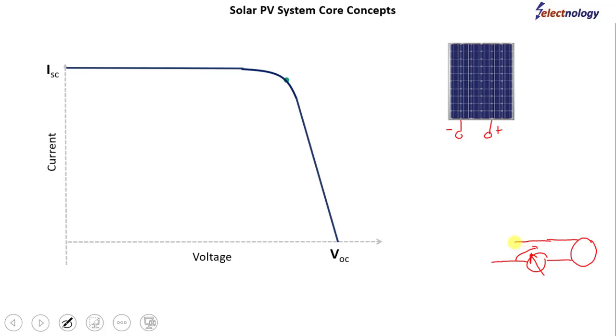Now assume that we are also measuring the current through this circuit, and we will place an ampere meter over here. Remember, the ampere meter is always placed in series within the cable. These are the terminals of the ampere meter, and we will connect like this. Now this negative shall be connected to this control device, and this is connected to the bulb.